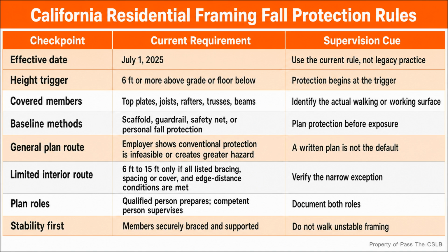First, I identify the roof condition. Is the triangle closed by continuous ceiling joists or rafter ties, or is the ceiling open? That answer points me toward either a ridge board condition or a structural ridge beam condition. Second, I trace the peak support. A ridge board needs the tied assembly around it. A ridge beam needs designed end support. I follow posts and bearing walls downward instead of stopping my inspection at the beam label.